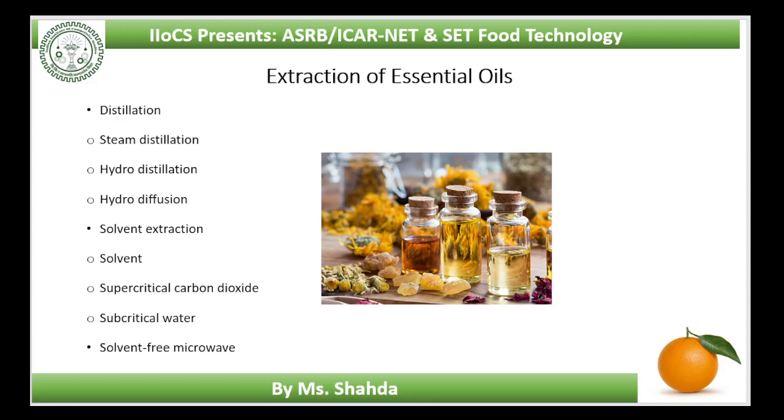Subcritical fluid extraction of lactones from kava root, compared to Soxhlet extraction with water. The extraction of ground sample with subcritical water at 100 degrees Celsius took 2 hours, but a shorter time, 20 minutes, was required when extraction was carried out at 175 degrees Celsius. Boiling for 2 hours and extraction with Soxhlet apparatus for 6 hours showed lower yields by 40% to 60% compared with that obtained using subcritical water.